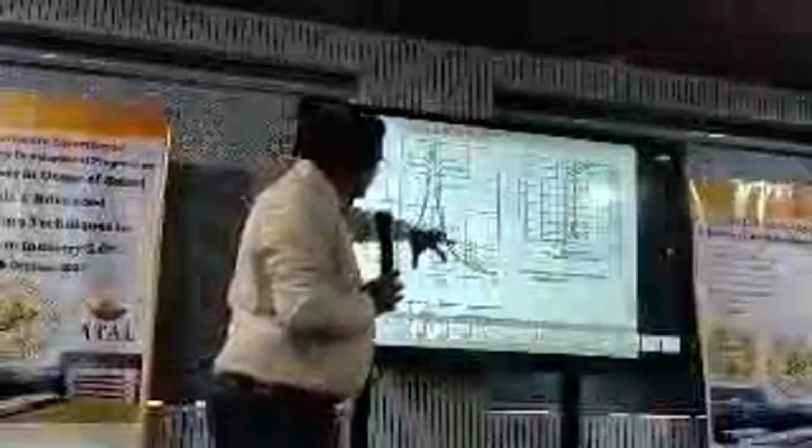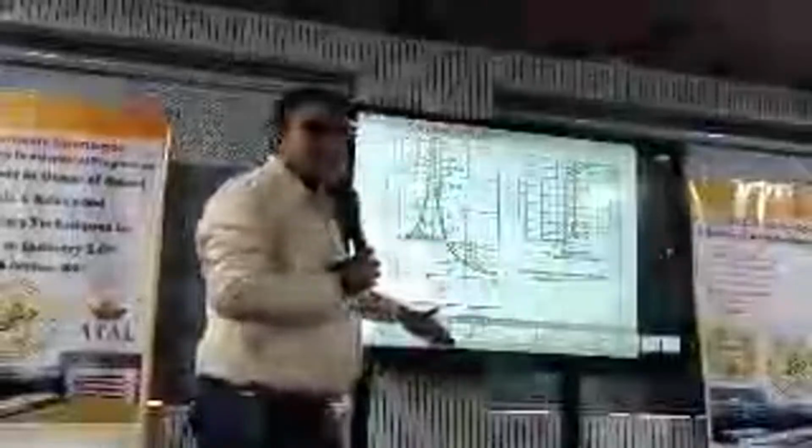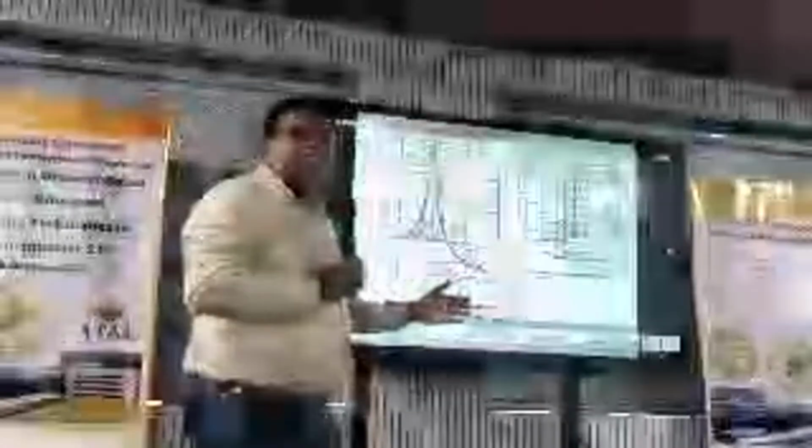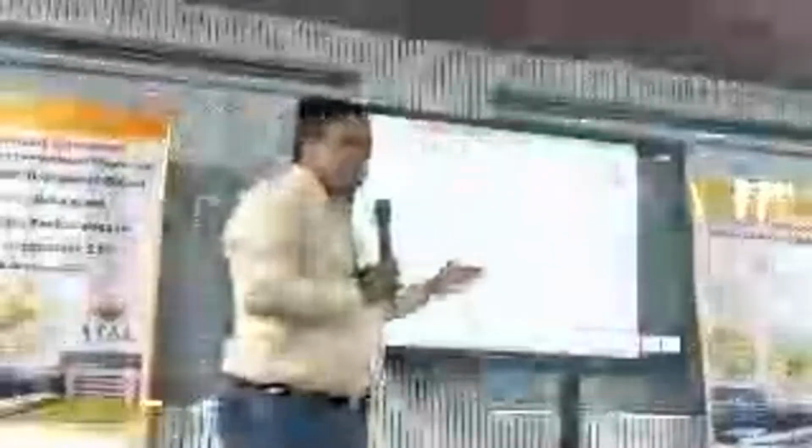This is called the stiffness control region. This is the damping control region, around the natural frequency. This is the mass control region. So we have to change the parameters, stiffness and mass. If you change the mass of the system, we can make omega greater than root 2, and then we get this region. Finally, for designing any equipment, we have to concentrate on this area. If you operate in this area, high vibrations will be there, so always avoid this region.